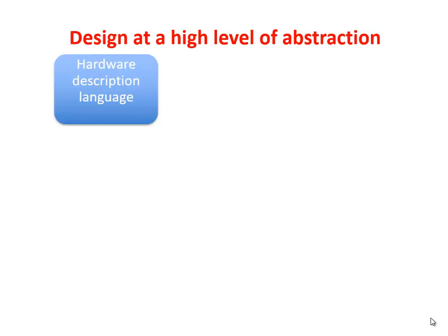Basically, one designs the total complete chip using a hardware description language, even with a behavioral description of the different blocks, so that one has a code base able to map and simulate completely the functionalities of the digital circuit.